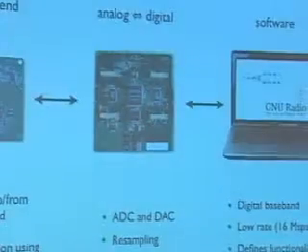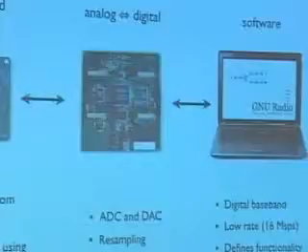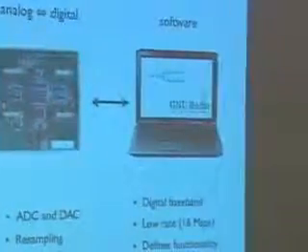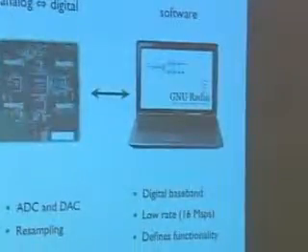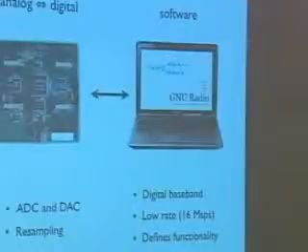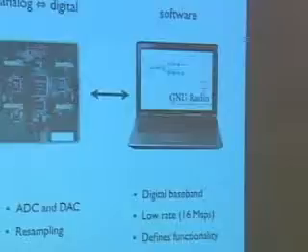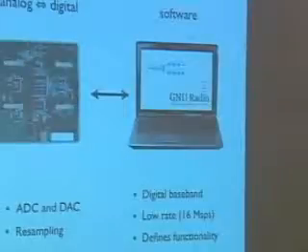On the right side, we have a standard laptop running the software radio itself. This is usually limited to lower-rate processing. Let's say I wrote 16 megasamples per second, which is specific for this setup. It can be anything from 10 kilohertz to, I don't know, 20 or 30 megasamples, which is probably possible in today's computers.